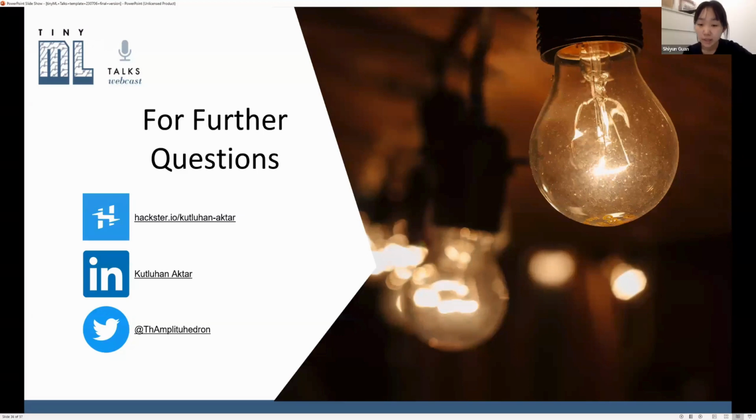Yeah. And another question from Andrew. What method do you use to validate the models to ensure they are accurate? First of all, after training my model, I collect a different test data set and upload it to Edge Impulse, which provides an already built-in integrated method to validate your model based on this test data set, real in-the-field data.